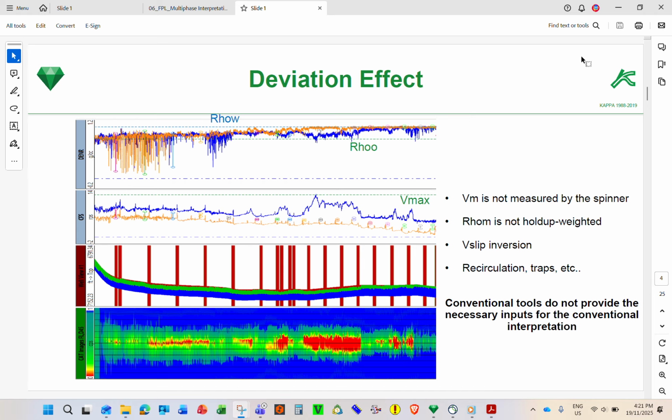So it's separated, segregated. So if the capacitance is here, okay, it's water. If the capacitance is here, it's between water and oil. So when between water and oil, you have the range. This one is oil. If your capacitance is here, between oil and gas. If you are here, it's gas. So it can detect the 3-phase because they are segregated. But if they are mixed, we cannot. We just use hydrocarbon and water, so 2-phase. Therefore, you might see the gas here, and you have the oil, and then you have the water.